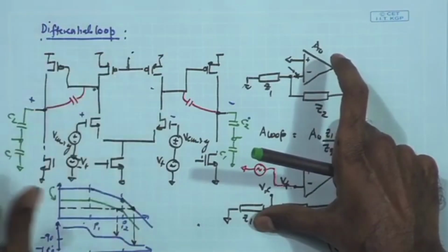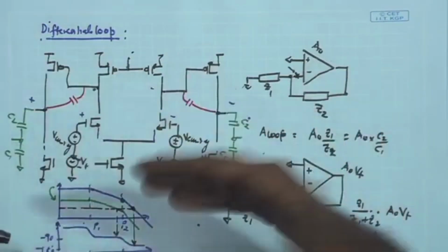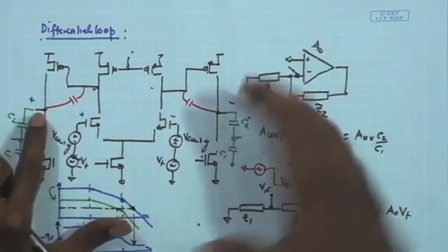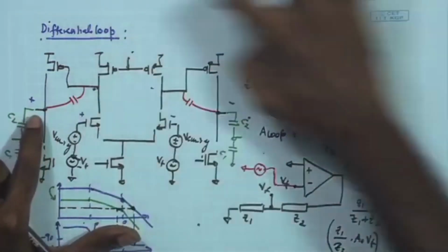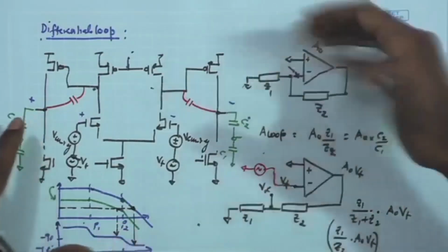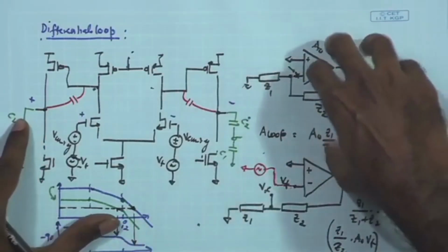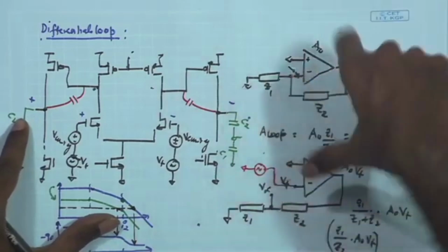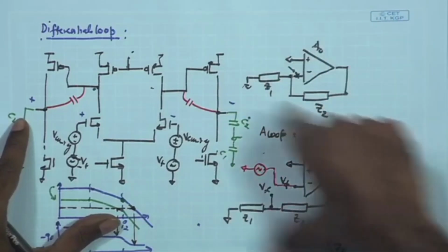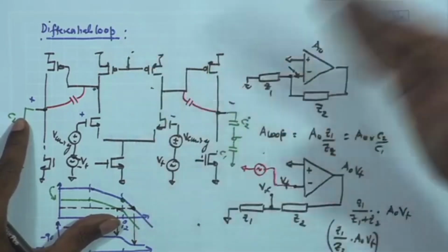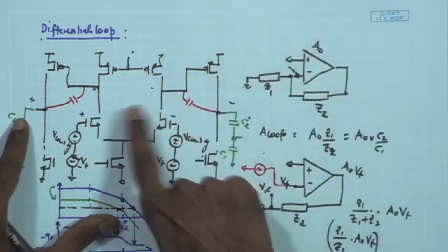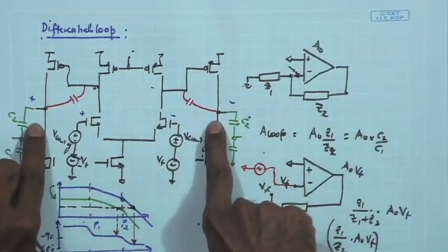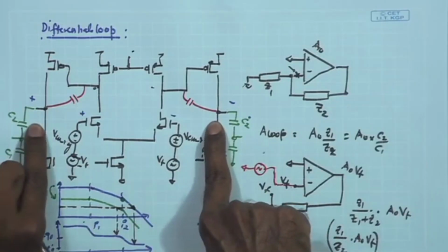This is just a DC bias point, and also here we have seen that for the combined common mode loop, if you are having a single common mode loop, we have also reduced the impedance of the common mode error amplifier by using a diode connected load, and as a result that is not going to contribute to a significant pole, and assuming that whatever poles are coming from that stage are much higher than the poles coming at the two outputs of our main differential amplifier.